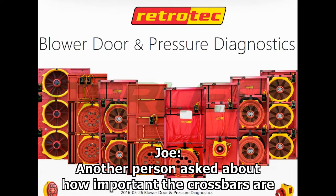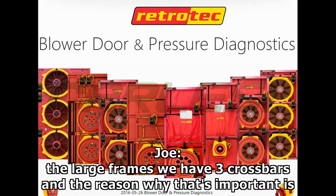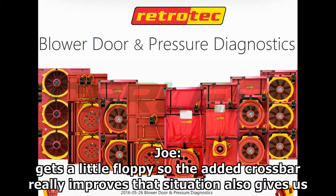Another person asked how important the crossbars are in the frame. On the new regular frames we have 2 crossbars, and on the large frames we have 3 crossbars. The reason that's important is that with only 1 crossbar, the upper part of the frame around the window gets a little floppy, so the added crossbar really improves that situation.